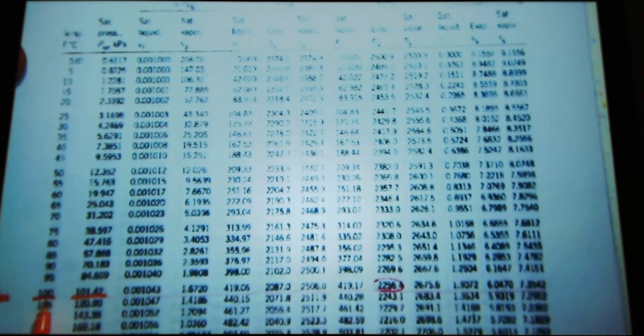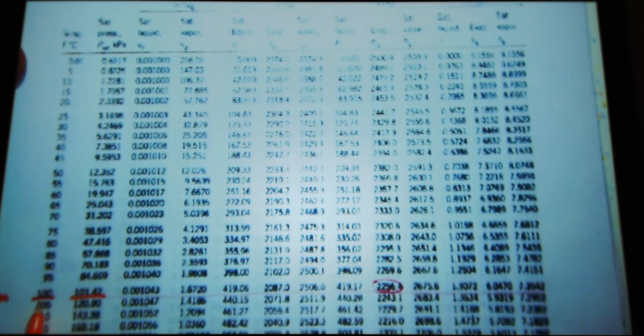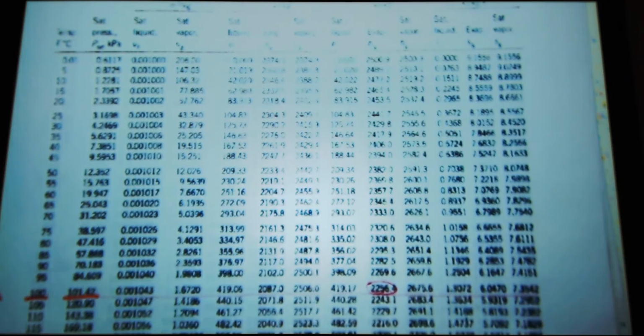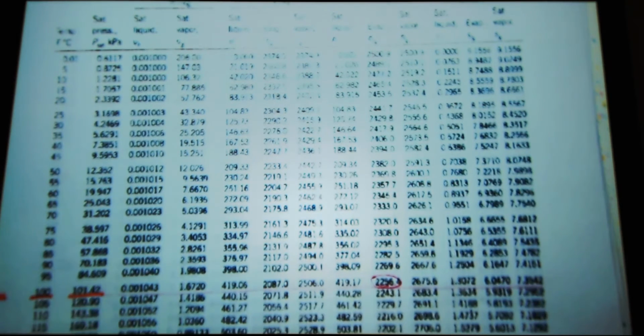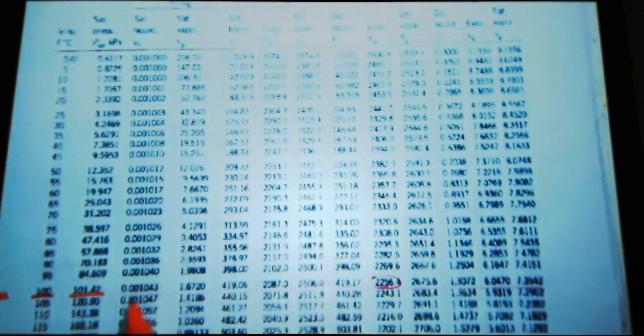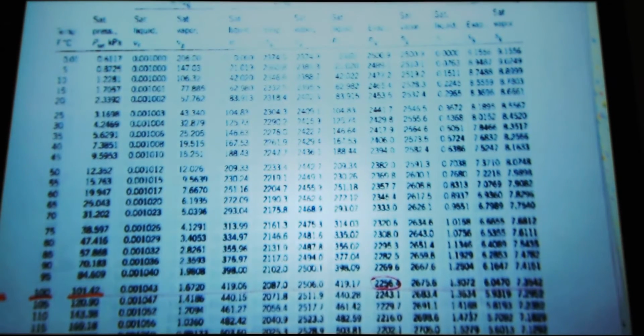At this temperature, given that I know the saturation pressure, I could have water at 100 degrees C within a pressure cylinder, so I could have a lot higher pressure than 1 atmosphere. But in this case, we're talking about water at 100 degrees C, like on your stove boiling. Then I can get the specific volume in the fluid, and this is the specific volume in the gas. So if I go back to one of these curves, let me pop it up there real quick.